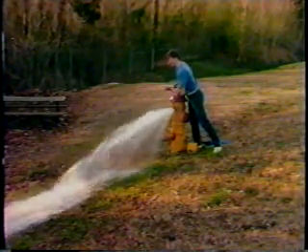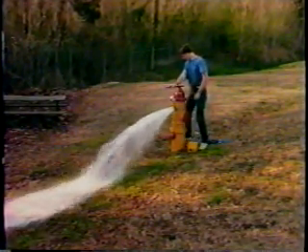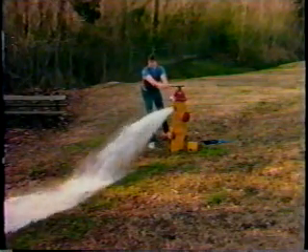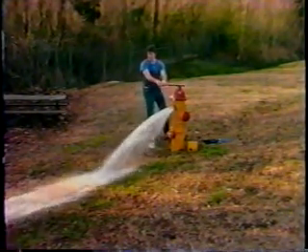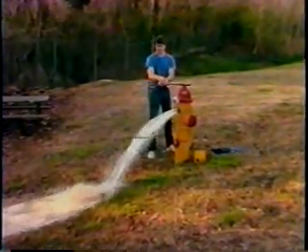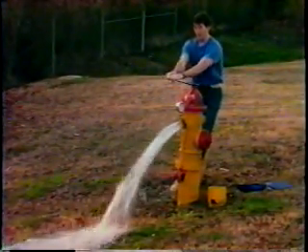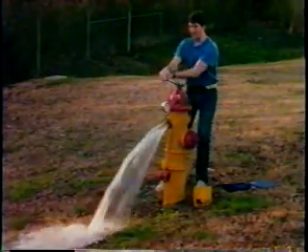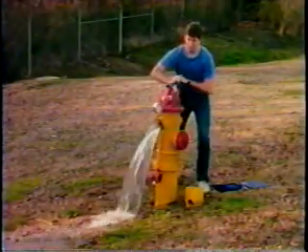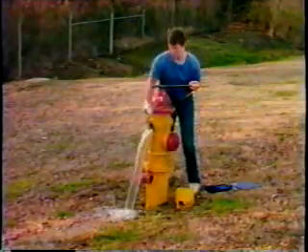The individual at the residual hydrant will be able to tell if one of the float hydrants is being shut too quickly, because he will notice the indicator on the gauge jump rather abruptly when the pressure surge from the closing of the hydrant reaches the residual hydrant.